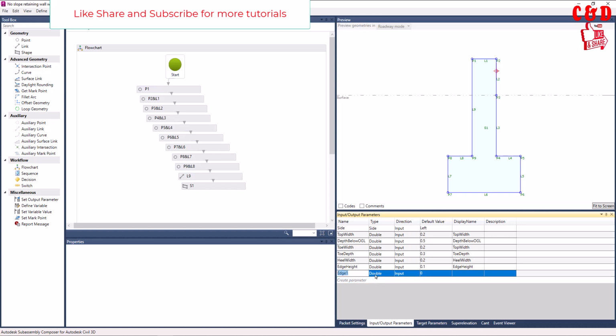Then there is another thing, type. You have to select the type. You can select all different kinds of types: double, integer, string, grade, slope, whatever. Or it's yes or no, conditional. When you have to switch, if it satisfies a certain condition, then do this, yes or no, then you have to put yes, no. And this is super elevation, as you must be familiar with the road, so we can use this. And axis of rotation can also be defined, the slope direction and the potential pivot region at which it will rotate, as an axis.